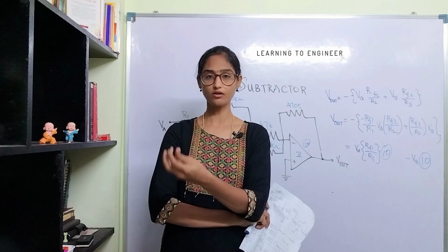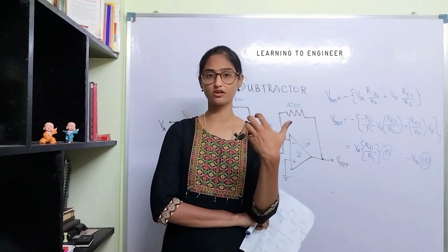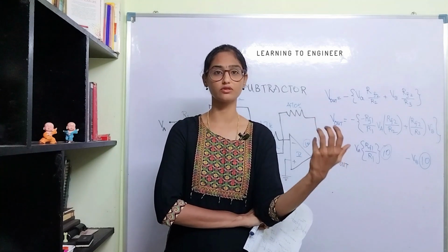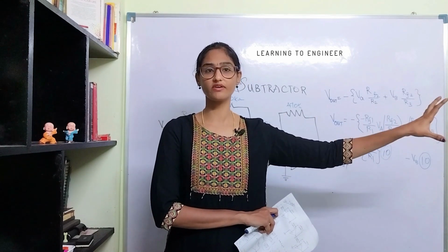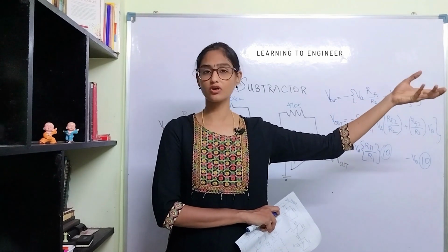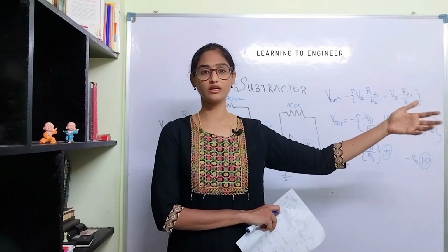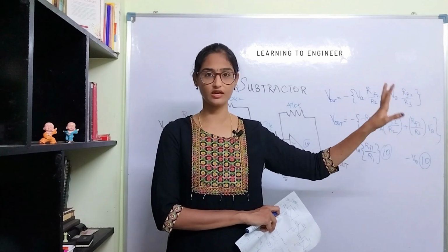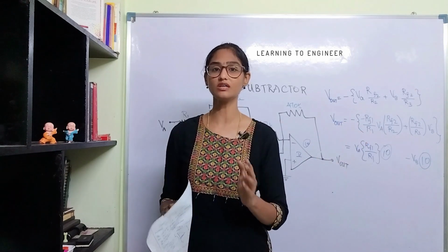This microvolts will be multiplied by the amplification factor of the op-amp to get a few millivolts, and that will be multiplied by another op-amp to get 1 or 2 volts. In another stage, it will be multiplied by 10 or 20 or whatsoever be the gain of that amplifier to get a large amount of voltage to be sent into the readout.